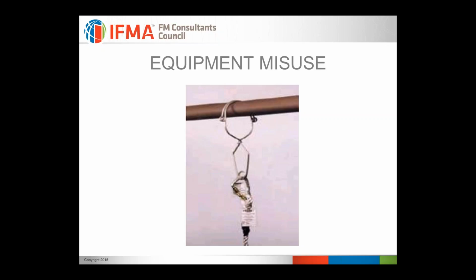Equipment misuse. I don't know the experience of everybody attending the webinar today, but my experience is that if you hand somebody a piece of fall protection equipment and don't give them any training or education about how that equipment is supposed to be used, the odds of them being able to use it properly are very slim. It's just not intuitive. Whereas if you give somebody a hard hat and say we have a policy on our site that you have to wear a hard hat, there's a pretty good chance they're going to put the hard hat on properly, right? Fall protection equipment is definitely not that way.